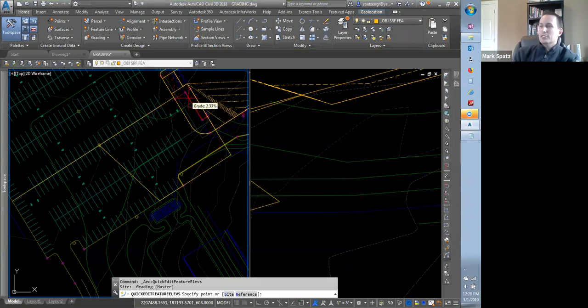And you can kind of use this just to verify like, oh, are those percentages okay? And if they're not, if you hit one that you're like, ooh, that's a little steep, well, you can just click and then adjust it to what you want it to be. Then whatever feature lines it touches will automatically adjust to match what you just entered. Like, okay, if you're telling me now this needs to be 3% down, that means this other one needs to go down too. And then you can say, okay, well now is that other one okay?